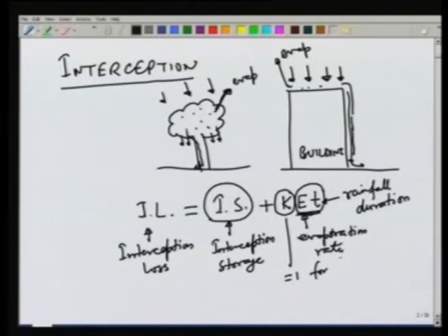A flat area, or let us say call it rooftop. But if you have leaves, then the leaves are not horizontal, they have some inclined surface, and the evaporation from this whole area will occur. So, K will represent the ratio of the area of the leaf to the projected area or the horizontal area.